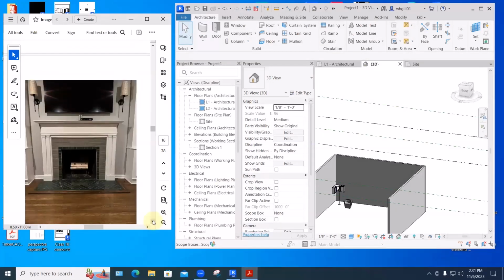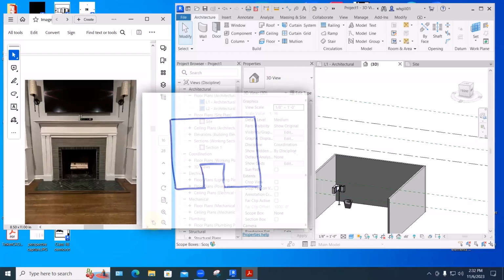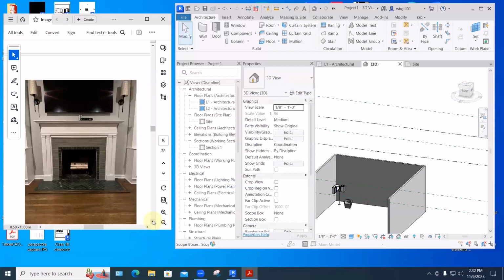For a fireplace where you've got a firebox that kicks back into the wall, if here's the wall in elevation and the fireplace is going to be here and there's a firebox, I would edit the profile of the wall to be like that. There's actually a hole in the wall that the firebox can go back through, so we don't have wall coming down just as soon as you get past the brick. Okay, let's take a break and come back and see what AI has to offer us.